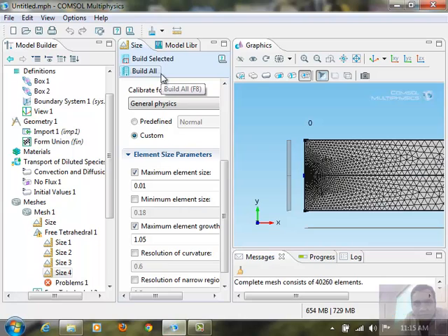If it is a boundary layer type problem where you have gradients restricted to a region, then you may want a very fine mesh along this edge, but you can give a higher growth rate so that in the middle you have larger elements. According to the problem, you can control this, and also you can iteratively go towards a more efficient mesh.